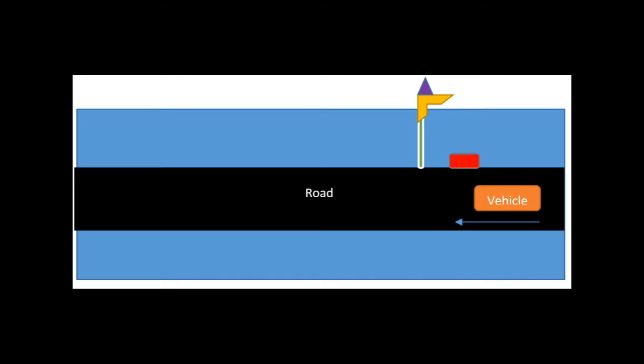This project needs an LED fixed to the green pole, an LDR above the LED structure, an ultrasonic sensor kept in the vicinity of vehicles, and an Arduino that controls the LED. As the vehicle approaches the ultrasonic sensor, it activates the LED after processing in Arduino. Also, there is a check in Arduino if the LDR value sensed is day or night. That is, the LED will only be on if the LDR senses a dark threshold.